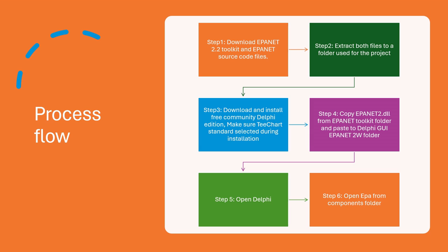Then we copy EPANET2.dll from the EPANET toolkit folder and paste it into the Delphi GUI EPANET2W folder. Without copying this file, our GUI will not build, because this DLL is responsible for solving the hydraulic modeling equations.